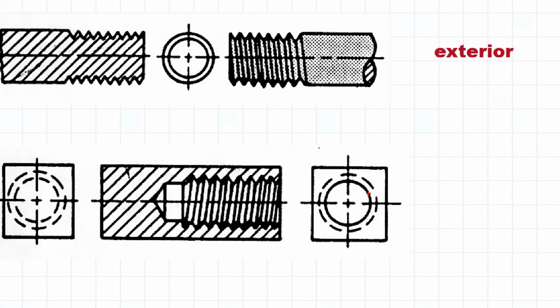But this is real important. What I want you to understand too is that we have a solid circle, and then we have a hidden circle on the outside of it. So regardless of the way the threads are displayed on the drawing, detailed, schematic, or simplified, this is what the hole is going to look like from the top. The threads may be shown a little differently in this view, but regardless, they're always going to look like this. Okay. So again, these circles are really representing what's called the minor and major diameters of that thread form. Okay. Does that make sense?